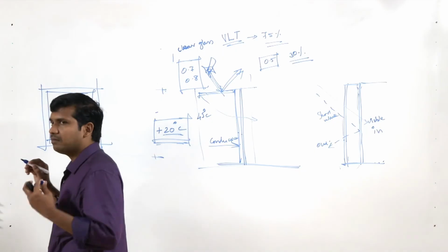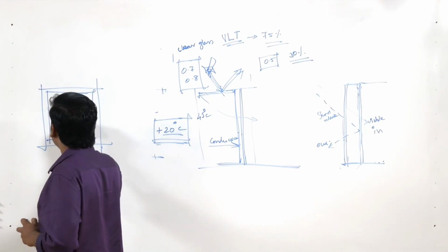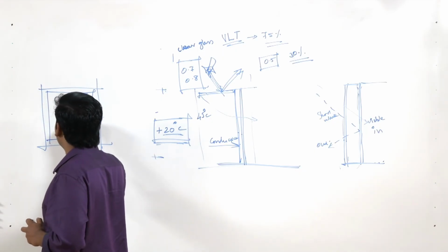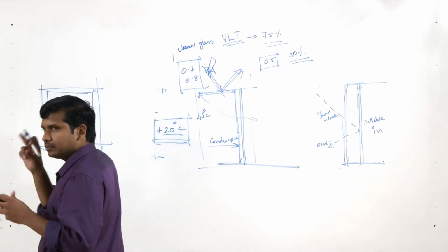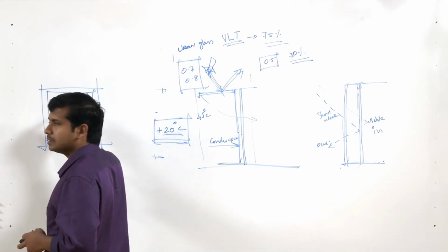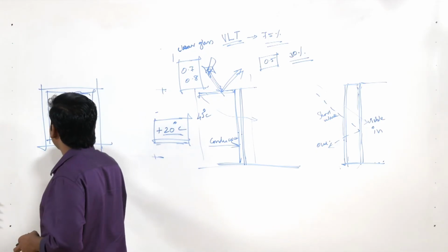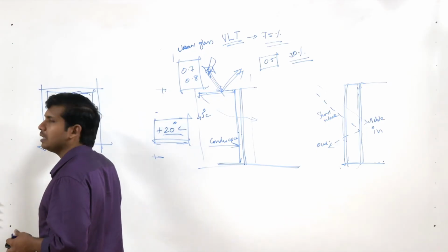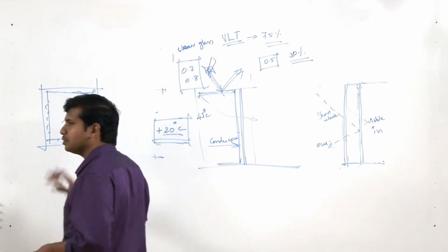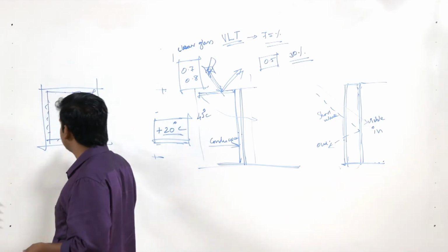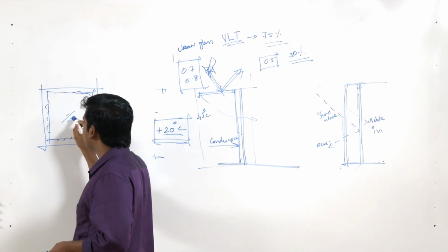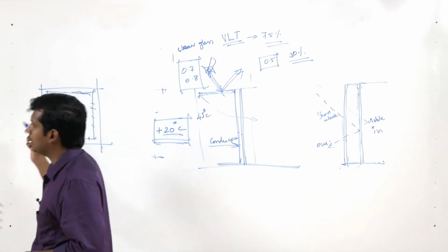So the U value that they give you is the center of glass U value, taken corresponding to what happens in this region. The edge effects, the effect of interaction with the typical frame system, are not considered. There is a minor difference, though not a huge impact, but still there is an impact between the center of glass U value and the edge of glass U value.